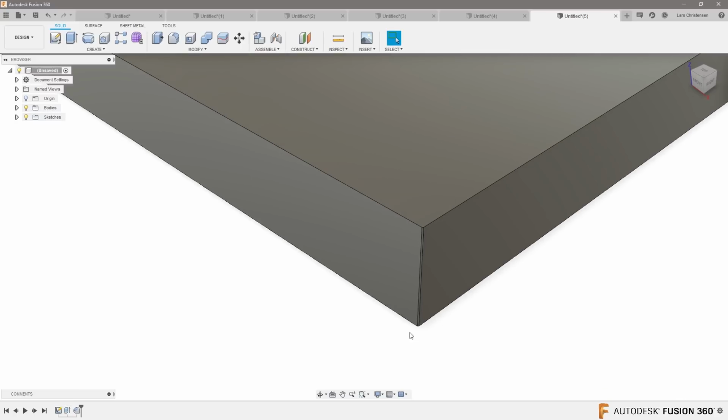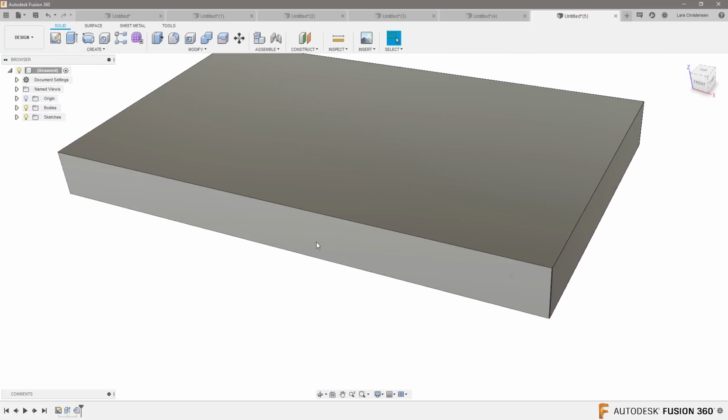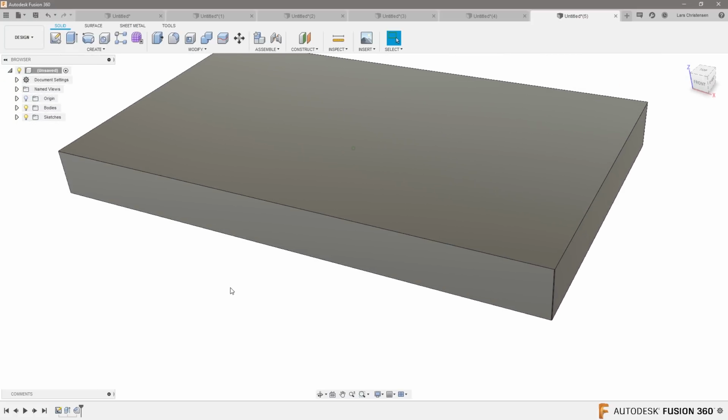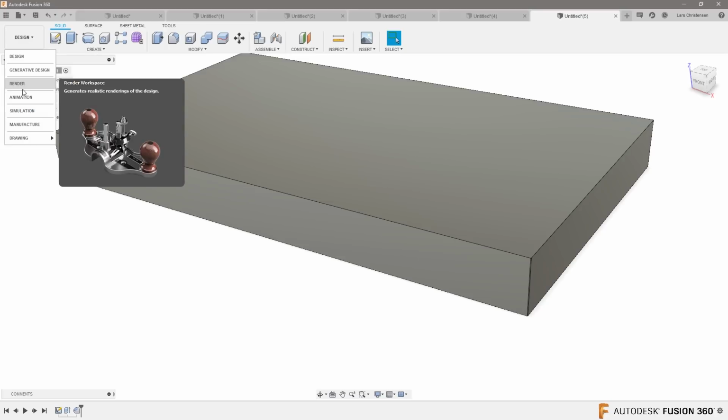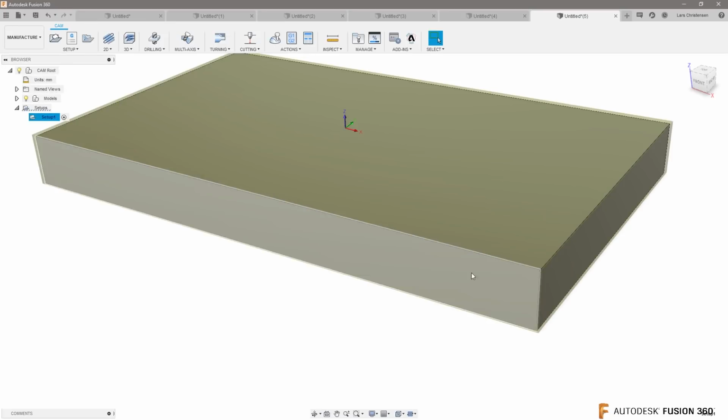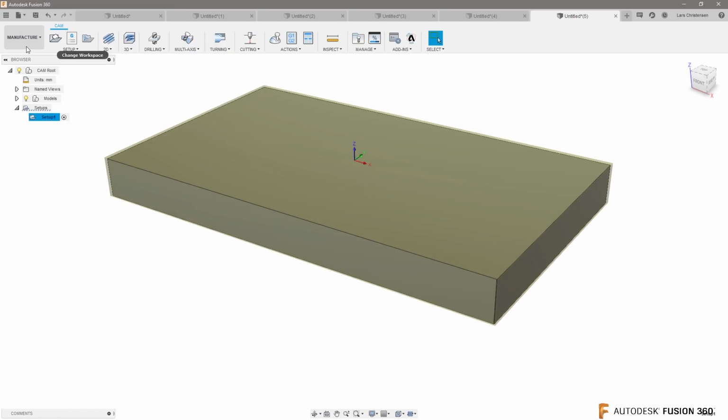If you're just breaking it in your model, then when you're machining around this part, you don't have to think about this corner being sharp. You can put a nice little chamfer on that. That's a nice little tip. Definitely if you're doing steel, if you've never done that, do that to all your outside edges, and you're going to love me for that.